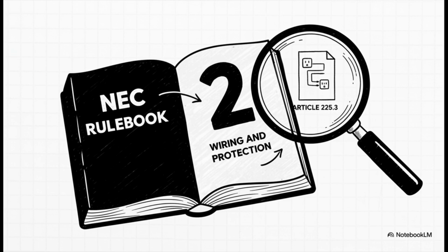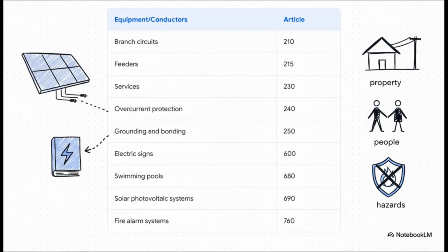The insight here is that the safety standard has to adapt based on the conductivity of the environment or how permanent it is. Take water. Water is the perfect example. The second electricity gets near water, the standard grounding rules from Chapter 2 are, well, beefed up dramatically. We see specific articles for marinas and boatyards, Article 555. And of course, swimming pools, fountains, Article 680. That one's famous for being strict. Extremely strict. And in a pool installation, the standard grounding from 250 just isn't enough.